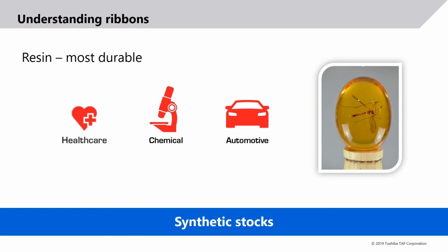So it's really important that you test resins before you order them, because there's nothing worse than having a print run that has to be rejected because it gets compromised when it comes into contact with a chemical on your site. So it's always, as I say, definitely worth asking your partner for a sample to trial, or asking them if they're able to do their own tests on your behalf.